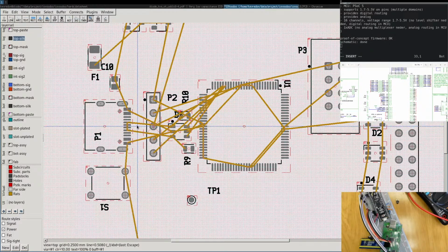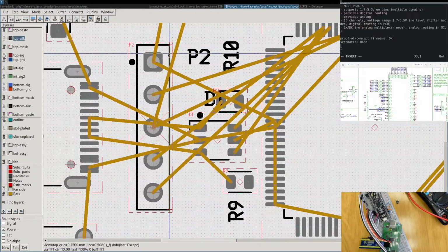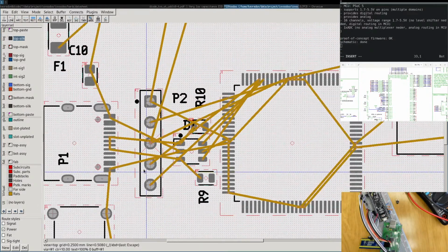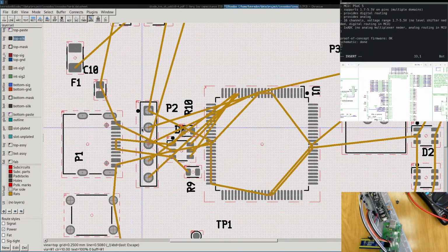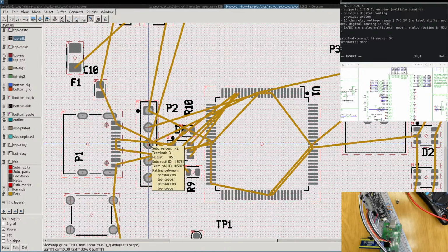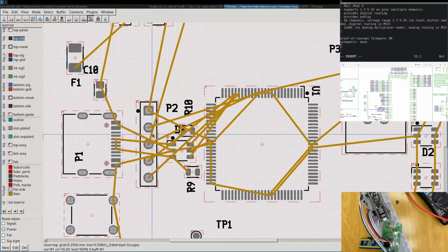For soldering, I have to solder first the first mount and then the screw hole, but this is generally the order, because if I had this connector first, then I have no way to contact these USB pins with the soldering iron. I cannot touch this pin. The connector will be in the way. This is something you don't see, but if you look at it in 3D, it's good this way. So have it routed to the sides.